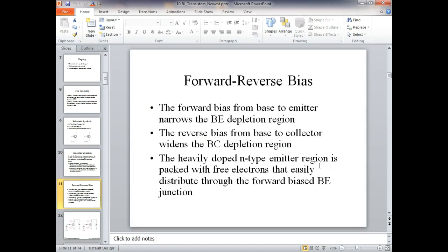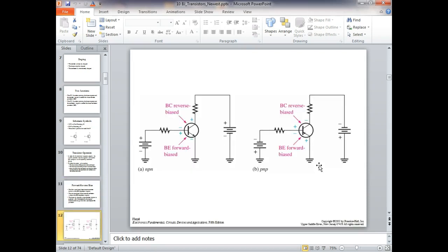And we talked about forward bias and reverse bias. So the base-emitter is forward biased, and the base-collector is reverse biased, right? Everybody okay? And that's the way we bias a transistor to turn it on. We also know that to turn it on, we have to get up to around 7/10 of a volt on the base. So anything below 7/10 of a volt, the transistor would be cut off. And when it's cut off, we have no current flow between the collector and the emitter, or current that we can measure, right?